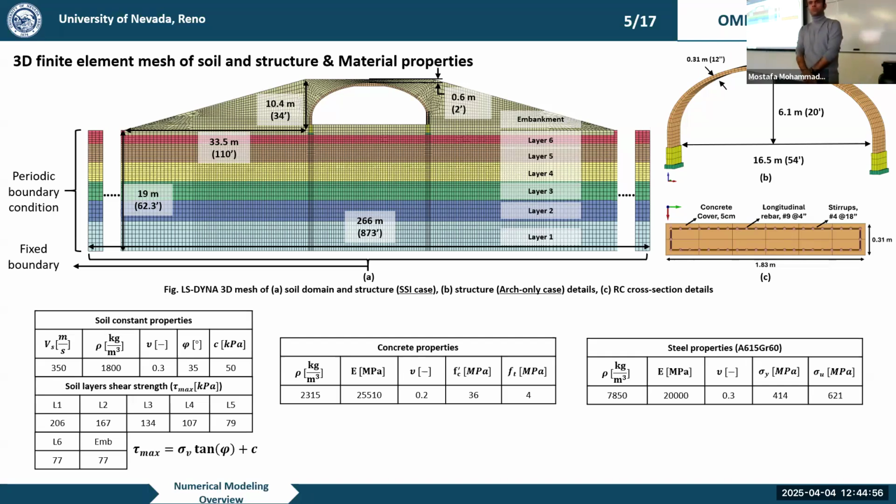Does it truly capture the interaction for the nonlinear case? With soil, there has to be a gap opening, right? There is gap opening. We did not have criteria to see if this gap opening and these slips are exactly what's happening. But since, as I showed you, the deformations are small and the failure wedges in the soil are not starting, we do not expect a lot of slips. So it seems to be working fairly well for now.